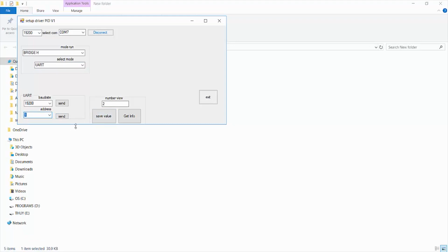And once again, remember to connect the direction pin to ground to reconnect to the computer if you have chosen the UART control signal. The data frame sent to the driver from the controller was explained at the PID speed mode, and they are exactly the same.